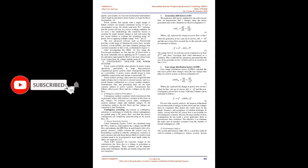The new advanced software such as PowerWorld provides a wide range of functions for power flow, security analysis, system stability, and other complete packages that can help researchers in their work, as illustrated in Figure 1. After investigating the IEEE 14-bus system using the PowerWorld Simulator, we find that line 10, bus 5 to bus 6, is the most vulnerable line by applying the N-1 scenario, and the substation represented by bus 2 is the most critical node in the system from the voltage stability point of view.